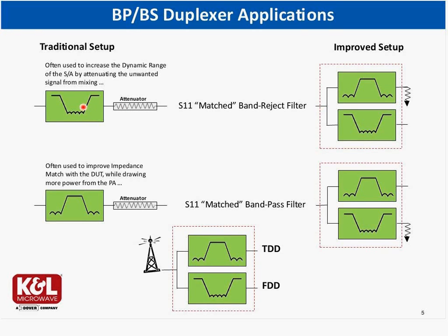And as Pat already talked about in his early presentation, this attenuator eventually will reduce the dynamic range of the setup. So every time you have a configuration of an attenuator and band reject in your schematics, I recommend that you think about replacing it with a bandpass bandstop, terminate it, and get back the dynamic range that was taken by the attenuator.